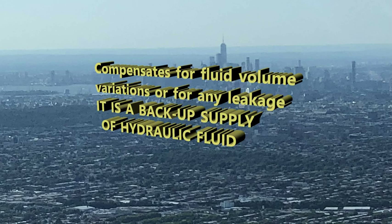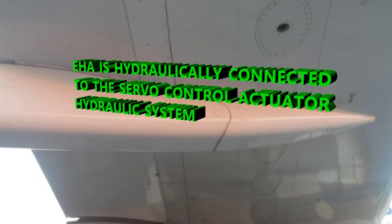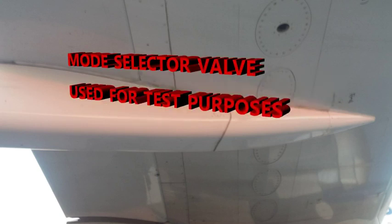The EHA, the actuator, is hydraulically connected to the servo control actuator hydraulic system. So it's all part of that, and it's just there to refill the EHA, and also for isolating it from the entire hydraulic system. And there are a few different valves that you'll see. There's a mode selector valve as well, and that's just for test purposes.